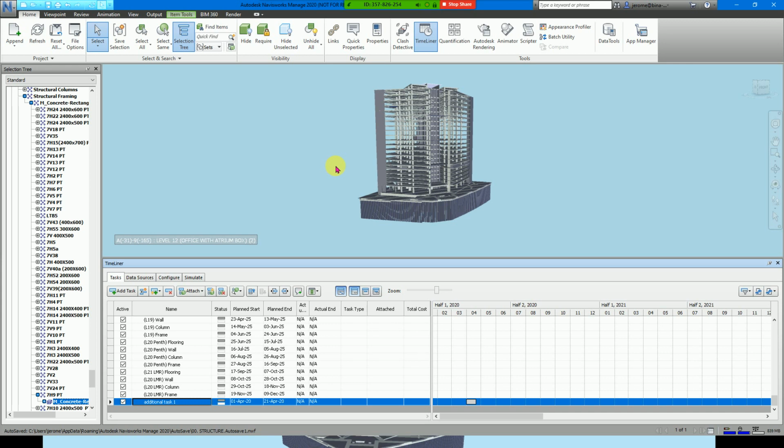Manually, yes. In Navisworks we don't have that kind of software that will automatically link the schedule. There's no such thing actually for the schedule and the 3D. When you integrate in Navisworks, it will not automatically run the simulation. You have to link it manually, because the planning was created by a different software like Primavera or MS Project, and the 3D was created by Autodesk Revit.